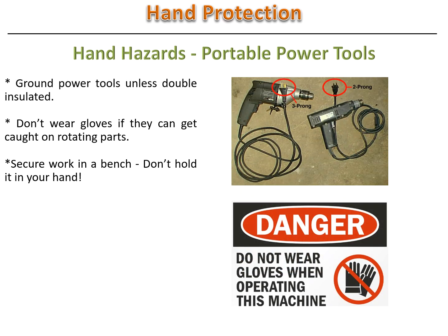Ground power tools unless double insulated. Don't wear gloves if they can get caught on rotating parts. Secure work in a bench, don't hold it in your hand.